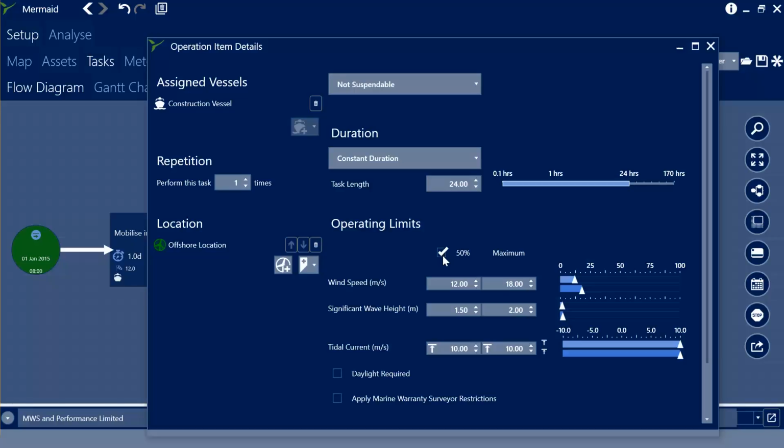When we're analysing a task, we may also want to apply some contingency to the work so that a sufficient length weather window exists to safely allow the completion of the work, even if unforeseen events take place. And in reality, we often consider contingencies on work to allow for any slight unreliability in forecasts. If we were to model this additional length as additional length on the task, we would require more work to be performed than the 24 hours specified here.